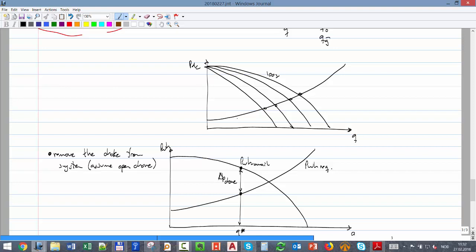One of them, you have to think, is for when you already have a system where you have selected a choke model, you already know how it performs, you know its characteristics, and you can very easily calculate that curve. And the other is very useful for the design phase. If you're selecting a choke, you say, I'm not sure what choke, the orifice, anything. The only thing I know is that this choke has to give me this delta P for that rate. And then I go to the manufacturer and I find a choke that is suitable for that. So you see the two ways of thinking.